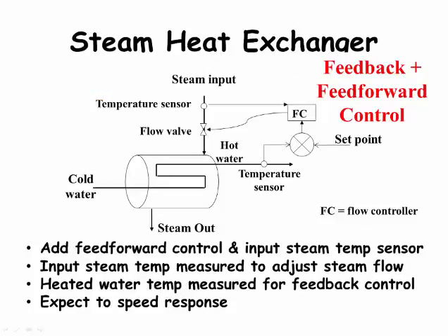This slide shows our steam heat exchanger with a temperature sensor in the steam input line. We now have feedback plus feed-forward control. We will use that steam temperature as an input to adjust the steam flow valve.